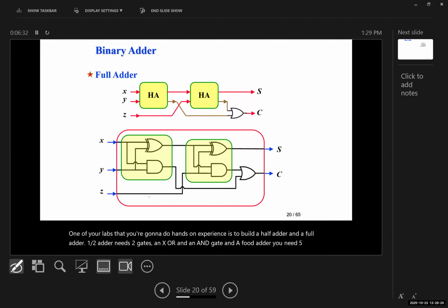And this is a carry propagation example that you can see. When the correct outputs are available, the critical path counts the worst case. For this example, A1, B1, C1 gives you C2, C3, and C4. So the delay again is that until we have the answer to A1, B1, we can't get to the next digit in A2 and B2 and so on.